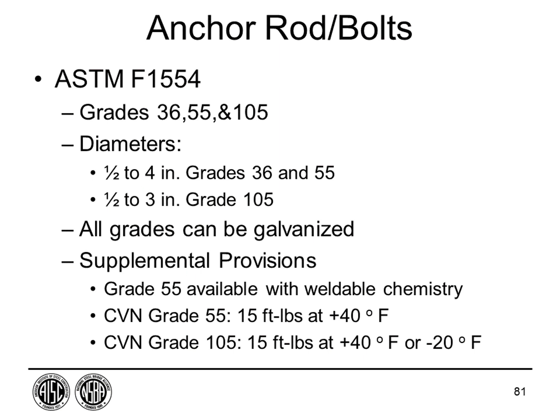There are supplemental requirements if you need to weld them, and they also have Charpy V-notch specifications. So these are set up and directly applicable for bridge requirements, and are very good, and they can all be galvanized, so they're very good anchor rods.